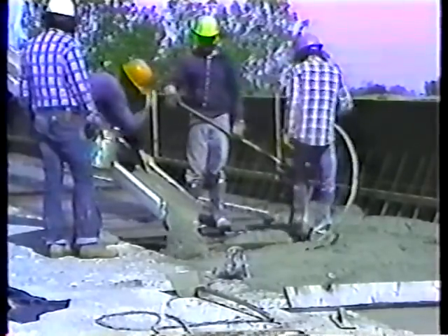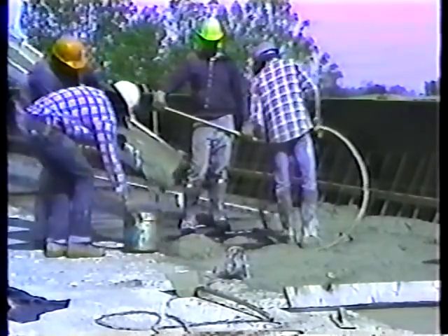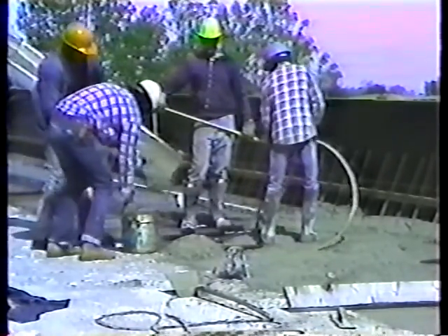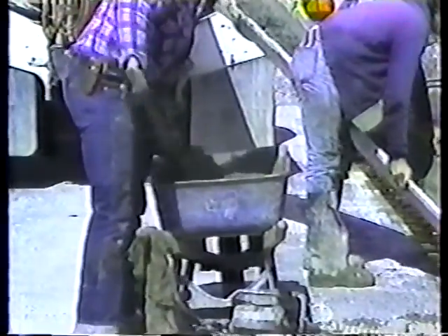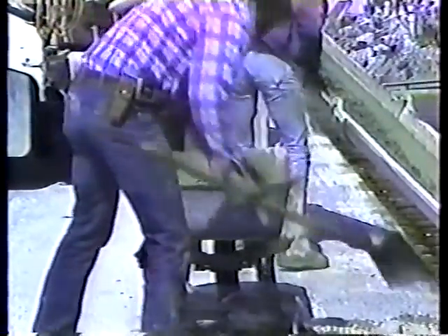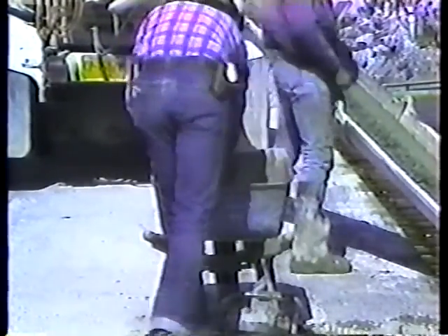Cutting the stream in half like this is unacceptable. The rim of the bucket will knock some of the large aggregate out of the sample. Remember, a reliable test calls for a representative sample. The sample should be mixed with a shovel, just enough to give it a uniform appearance. Then it should be covered to protect it from the sun and the wind. Don't let it dry out.